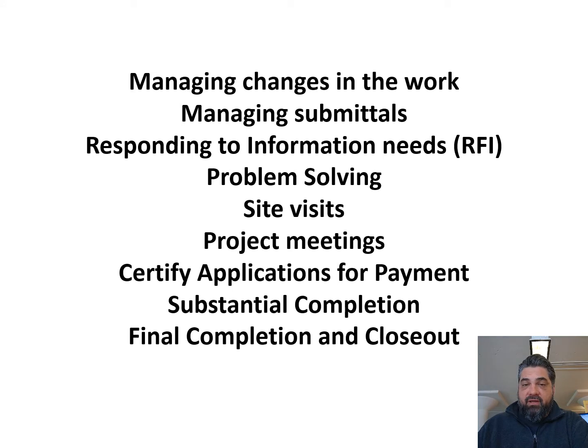You're going to be managing submittals. So in your specifications, you have requested all of these different submittals to be submitted for each scope of work. And so you're going to have lots of them coming in, and then you're going to be sending them back out. You will be responding to requests for information, or RFIs.